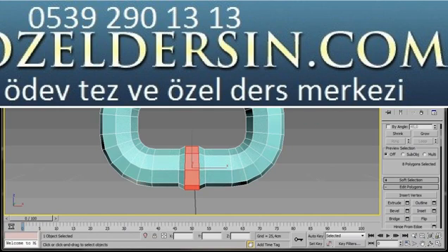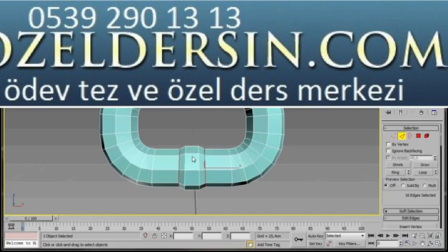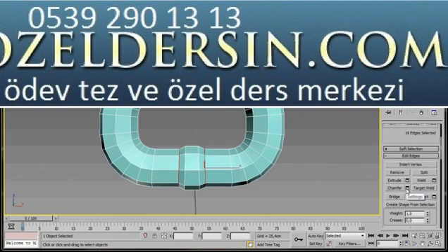I'm just going to come back to the panel now and select my edge mode. Notice now I have these 2 edges selected. We'll give them a small chamfer, so I'll come over and click on the small settings icon for chamfer. We'll just bring this down. Bring this right down to 0, and then we'll boost it up to 0.1, then press OK. That will give us a nice little chamfer there. This is going to be the little welded piece that's in the middle of a link.